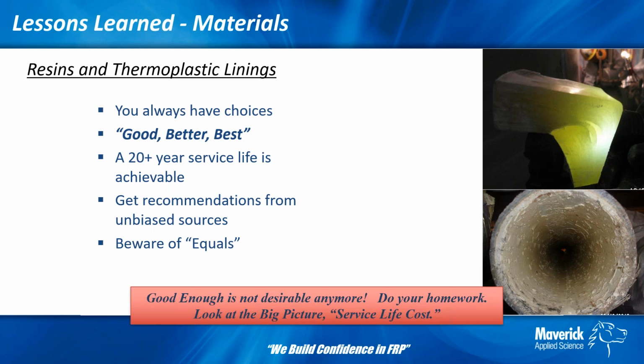So they'll all say it's good for it, but when you look at the cost of replacing pipe, bringing a unit down in many cases, or at least a system, for probably not less than 5 to 10 days, when you look at lost production, to bring it down every 10 years, rip it out, buy new pipe, and put it in, it really doesn't make sense to buy that cheaper material. Ideally, some of these applications are challenging, but as close as you can get to a 20-year service life is really how we would recommend selecting resins, as well as our thermoplastic linings.